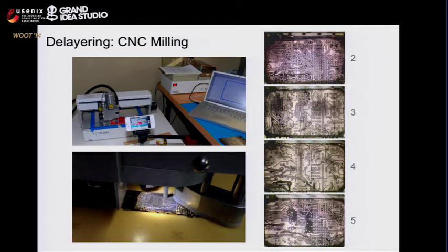So with the milling machine, it worked great, and here's my setup. I had a T-Tech QuickCircuit PC board prototyping machine, and basically set up a little area of the board to mill out. But once I could start seeing the next layer under the substrate, I just used the fiberglass scratch brush to manually get down. Otherwise, you wouldn't ever be able to get a totally flat result.